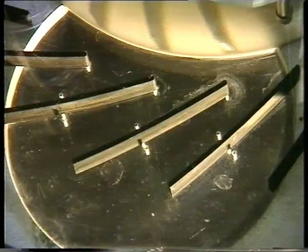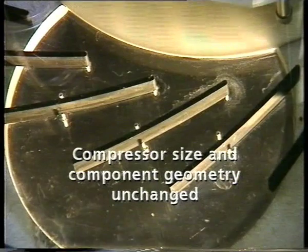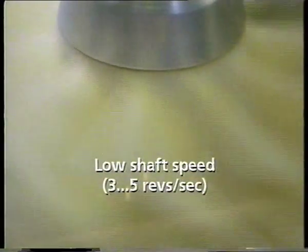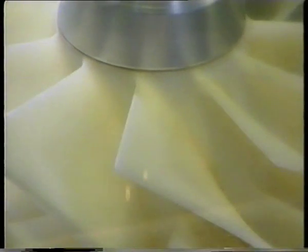Compressor size and component geometry were kept unchanged. The incompressibility of water has been accounted for by a corrected shape of the blade height distribution. To achieve Reynolds similarity, the shaft speed was reduced to typically 3 to 5 revolutions per second.